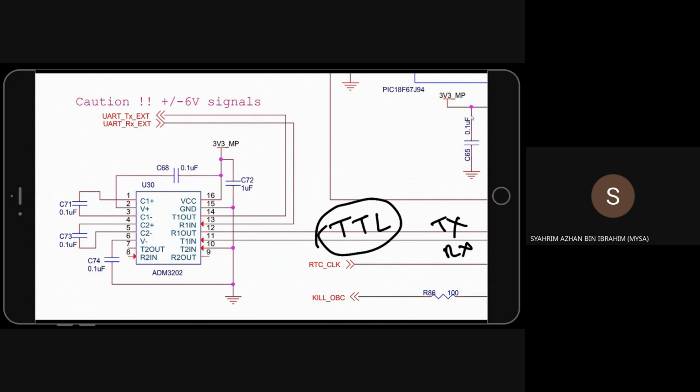Sorry, this one actually needs to connect to the computer PC. This basically goes to the FAB. You need to connect it to a serial reader, and the serial reader will be connected to the PC. But this voltage is a little weird. Not weird. You have to find a dedicated serial reader. So I connect this to the UART to USB converter to the PC. Can you do this one?